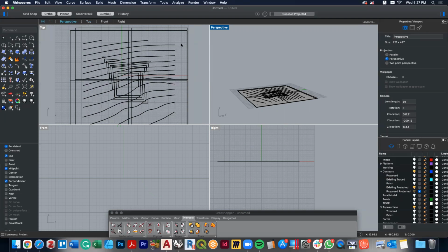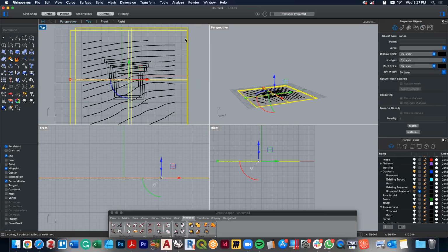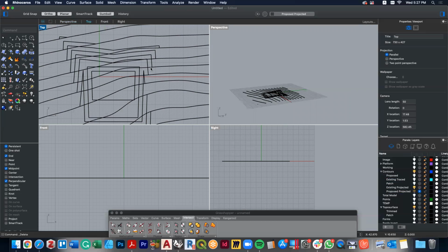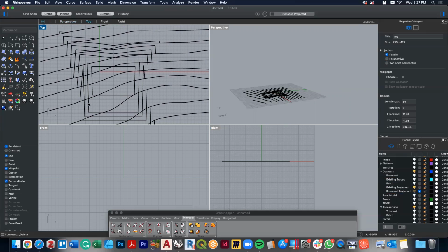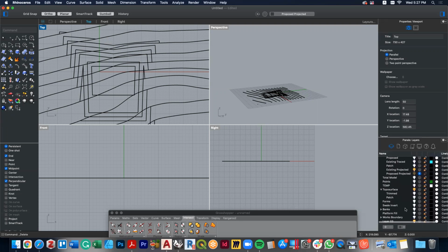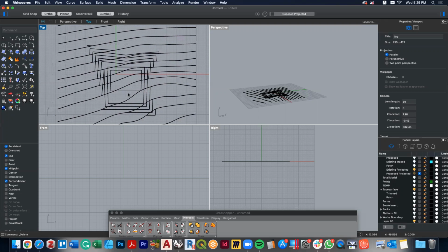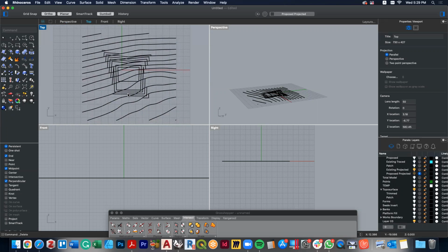And so I'll turn off, what is this? We don't need either of those planes. We just need these guys. And what we can also see, which is interesting here, is because of the grade and the interval, the swale is not entirely shown. So this is where turning on the swale invert and editing the swale invert is a useful thing for us to do. And so this is the starting point where we're now beginning to craft an image from this.